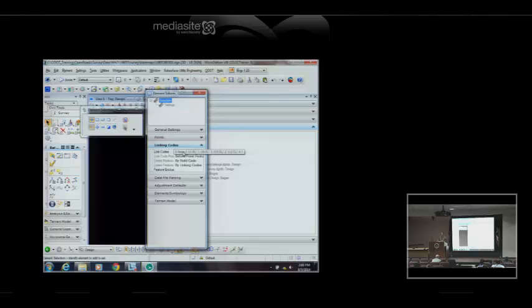For example, I'm hearing from some of the districts that if they put the mapping code after the feature code, the Trimble Business Center stuff will do all the line work. So traditionally, ODOT has put BL asterisk space code name. Now some of the districts are doing code name space, then the mapping feature after it. So that's something that can be changed in here. Where is the mapping code? Is it before the feature code or is it after the feature code? Well, right now it's set before in the ODOT. That's another example of something that can be changed.